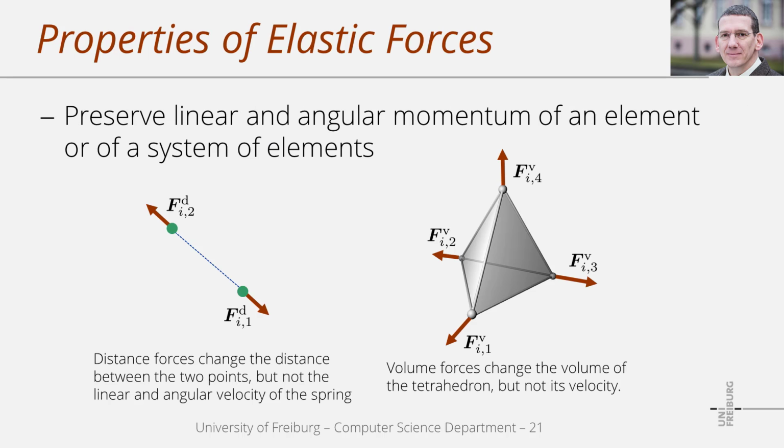The elastic forces that we compute from the gradient of the elastic energy have interesting properties, and these properties are actually the main motivation why we generally apply the concept instead of just using some arbitrary forces to counteract a deformation. One of the most relevant properties is the fact that the elastic forces just counteract the deformation. They do not change the linear or angular momentum of a deformed element.